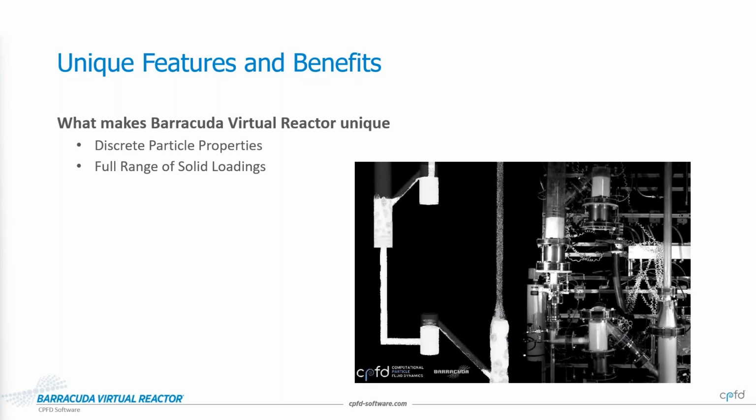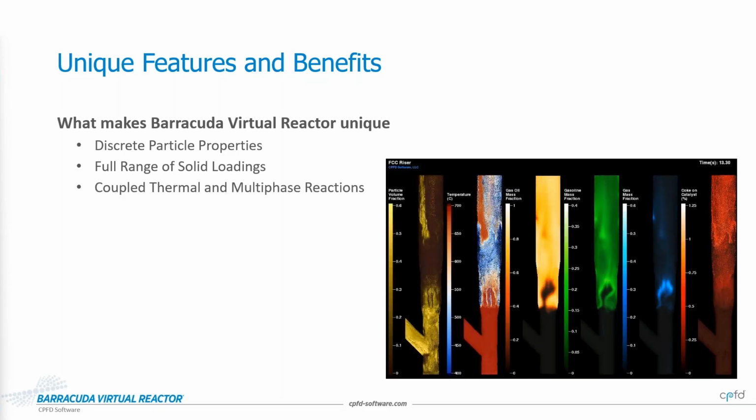The next distinctive here is the Barracuda is able to handle the full range of solids loadings. This is an older video of an experiment next to a simulation at a test run out at the NETL laboratory, National Energy Technology Laboratory. And what you see here is regions that are fairly dense, more bubbling, some turbulent, some very dilute systems, some areas where there's no particles at all. It handled in the same simulation at the same time without knowledge in advance of where things are to be dilute or dense. The whole range of solid loadings is able to be modeled there.